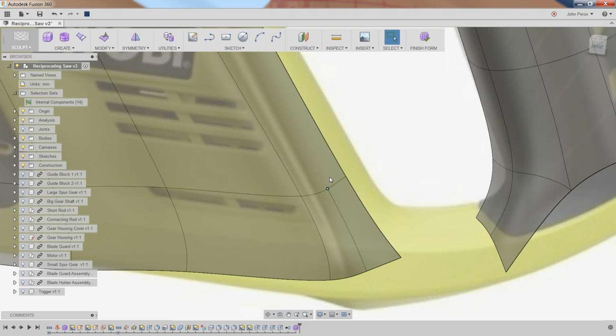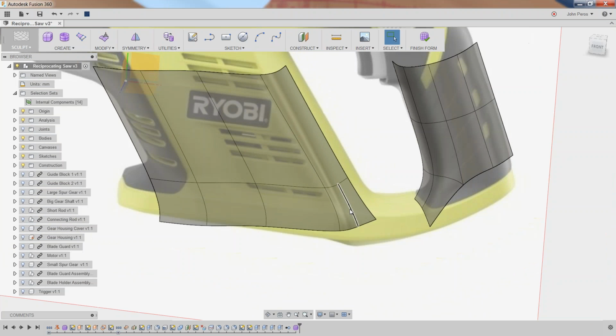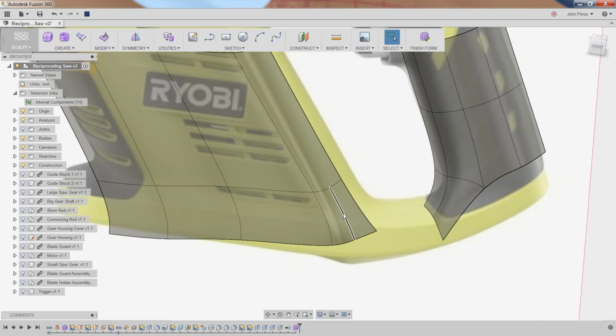It's a T-point. T-splines is the only mathematics in these freeform type of tools that can solve the curvature at a T-point like that. So in other tools, I would have to continue the detail all the way up the model, and I would end up with detail that I don't need. And the more detail you have, the harder these models are to control. So again, from a basic surfacing perspective, this makes it really easy to learn how to surface inside of Fusion.